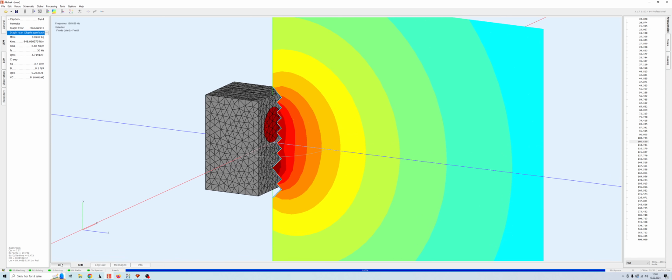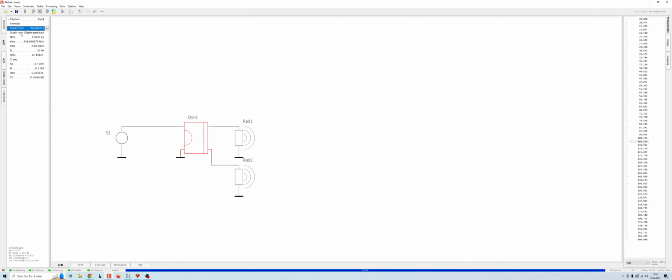We can see here, if we go to diaphragm front, for example, it tells us the SD. This is about 110 centimeters squared, as opposed to 132, 133 for the Purify woofer. So the results are going to be a little different, but the point is mostly just to get an idea of how you can set up this lumped element model.